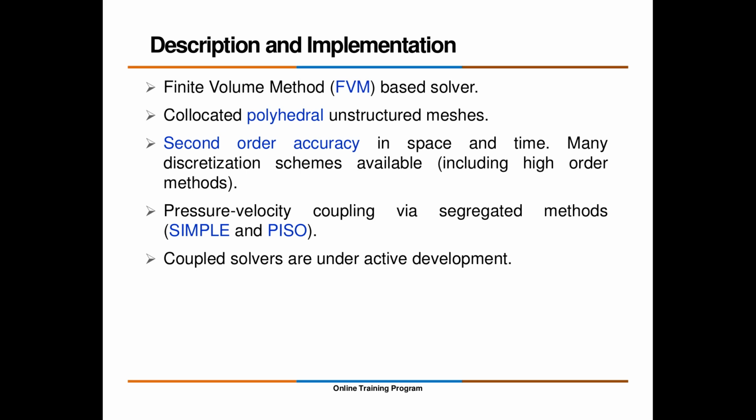It is able to work with polyhedral types of unstructured mesh. So you need not worry about any type of element. You can work with hex, tet, polyhedra, any type of hybrid mesh, unstructured or structured mesh. It is able to adapt to all your meshing. And the beauty of OpenFOAM is that it is parallel. You throw any mesh at it, it is going to work in a parallel environment.